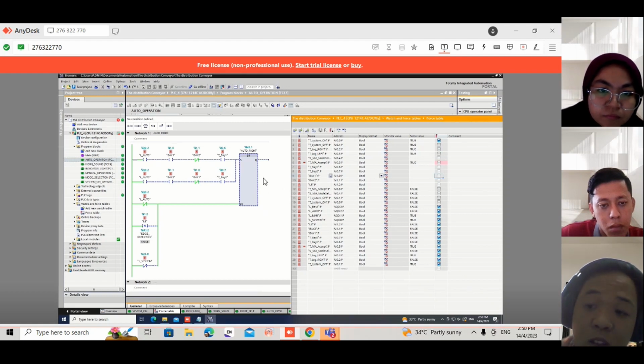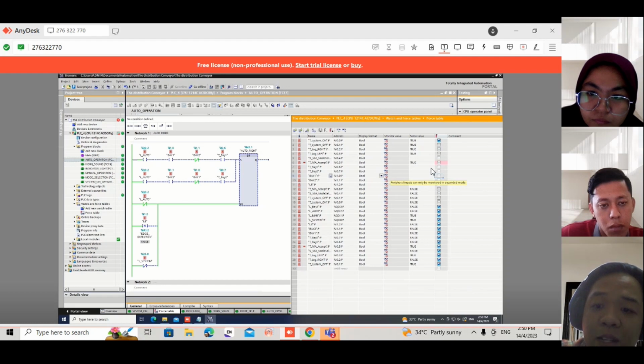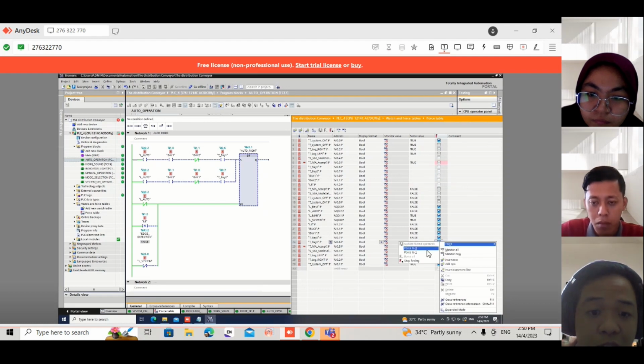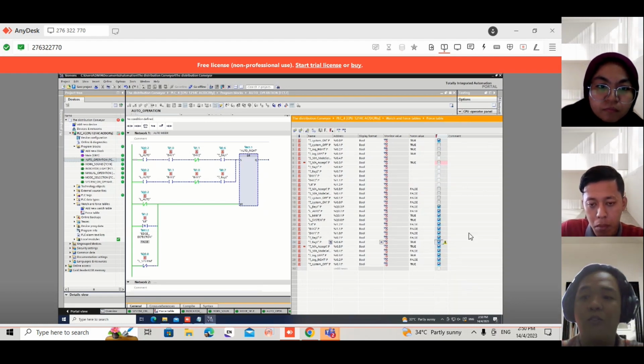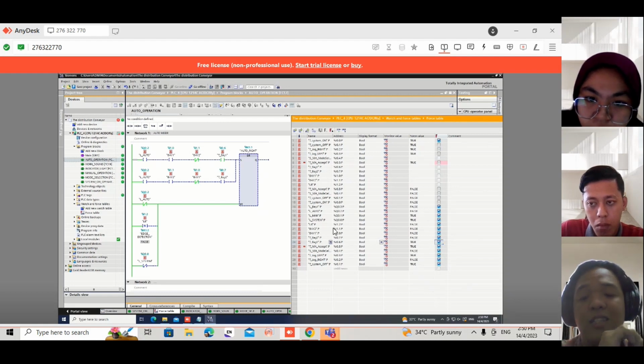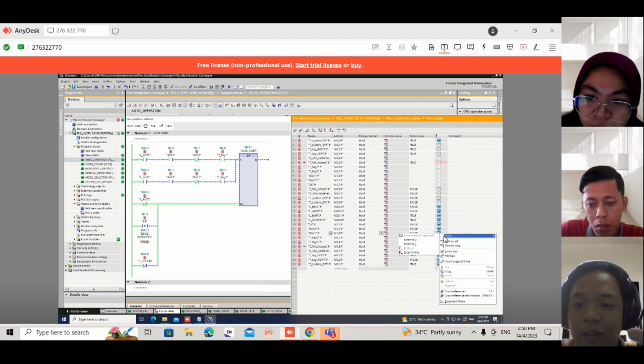We want the conveyor belt to stop as soon as the part passes through the light barrier, which is like a special gate that the part goes through. So as soon as the part goes past the light barrier, the conveyor belt should stop, even if auto mode is still on. Everything else in the system will stay the same.